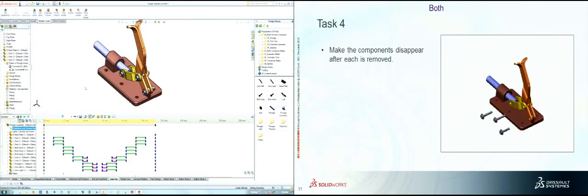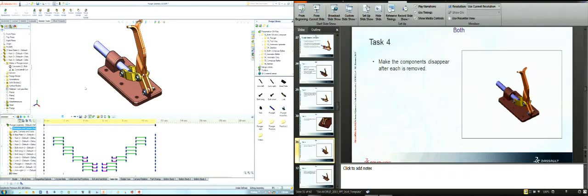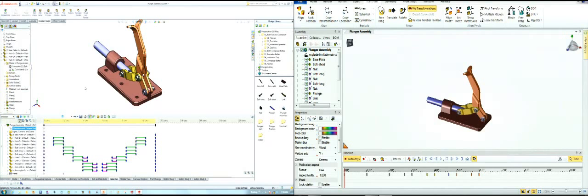Okay, so as we said in the beginning, when we animate things, what do we animate? Components, properties? Well, fading out a component's a property. So in this case, that's what we're going to do. This is the sequential explosion, and we can see the nuts go out there and then the bolts go out. But when the nuts get out to here, the next thing we want them to do is fade out. Okay? So a good thing to do, and this is just a tip if you're using Animator, here's my 3 nuts on their tracks.